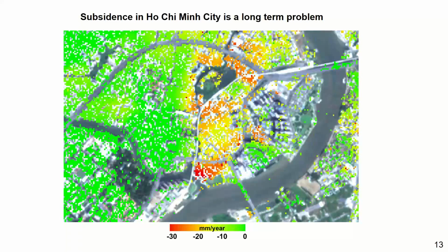They raise it a little bit higher as a function of time, leading to many houses nearby being lower by nearly 1 meter. So you see here, the street is higher than the houses nearby by 1 meter. It means that when there is heavy rain, the houses living here become something like a water town. A lot of water, like a river inside here, everywhere becomes a river when it rains. And it's also easy to recognize that this area is not really stable, and because of that problem, people have to try to maintain and increase the elevation to deal with the subsidence also.